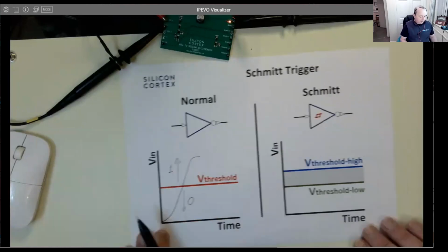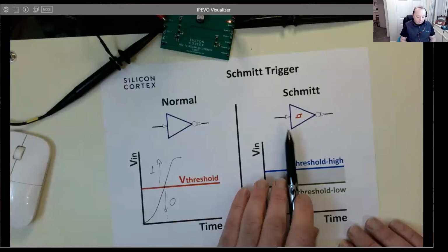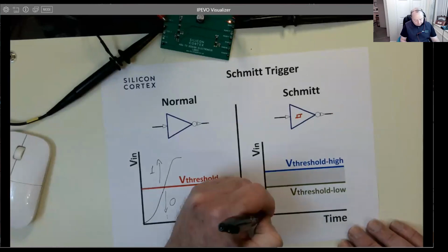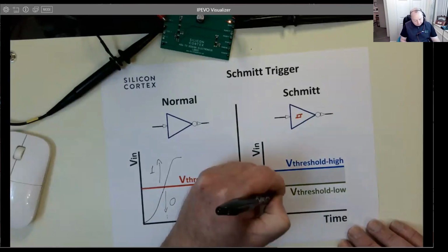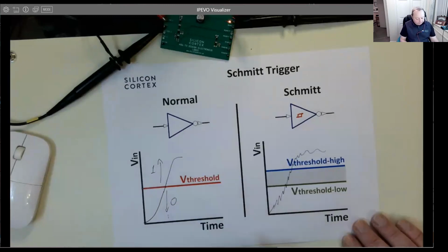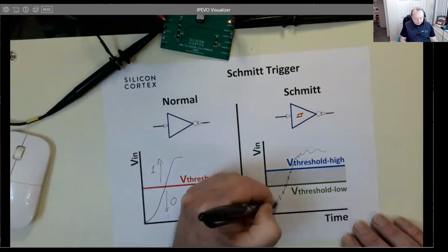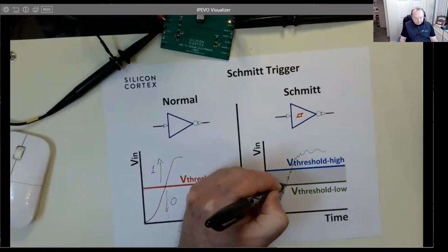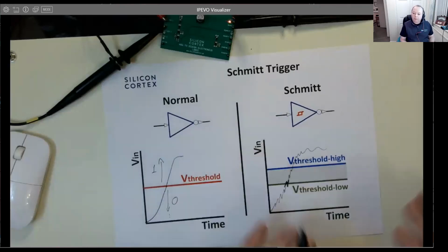There's then something called a Schmidt Trigger, where it has 2 threshold levels. So let's say you're dithering, I'm a bit of a ditherer. When it gets past the first one and it triggers, it doesn't matter if it dips below it again, it won't then cause a problem with the output.